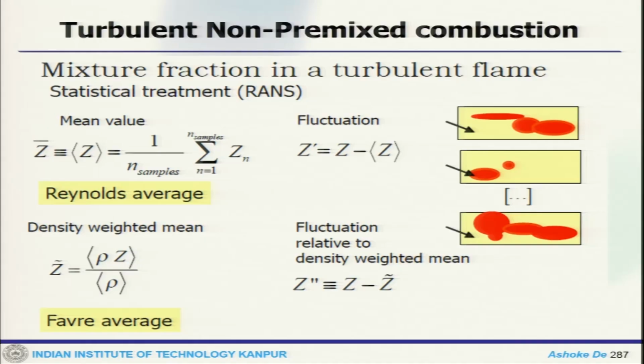Okay, welcome back, and let's continue the discussion on the mixture fraction kind of model. So we have looked at the basic system like the Burke-Schumann kind of flame and what happens when we have single step reversible and irreversible chemistry, and whether we have infinitely fast chemistry or finite rate effects. We have seen how it changes, and we established a simple equation for the mixture fraction, species mass fraction, and the temperature as a function of Z. And then finally we got the relationship between the enthalpy and mixture fraction.